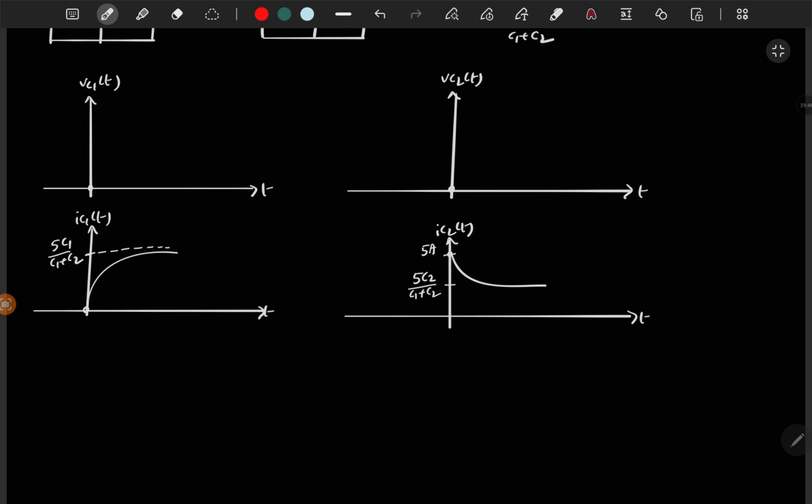So now see, the steady state currents are finite for both the capacitors, right? I mean, it is constant, finite and constant. Which means if you pump a constant current through the capacitors, then it will charge linearly, which means the capacitor is not going to some steady state final voltage, it is going to some steady state final current, which means it is still in the charging phase only. I mean, there is no steady state for it.